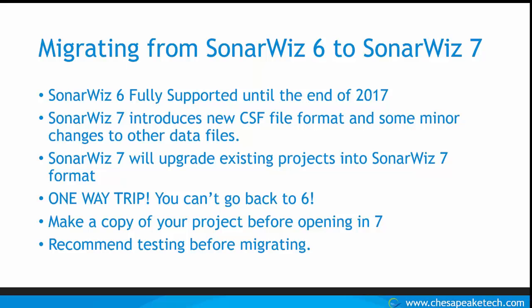And probably the best way to move forward with SonarWiz 7 is to start new projects in 7 or do your testing in SonarWiz 7. Finish whatever work you've done in SonarWiz 6 and just keep going with that. There are some nice new tools in 7 and we can promote them, but there are several places where it's actually better to just start a project completely over from scratch in 7 rather than promoting it.